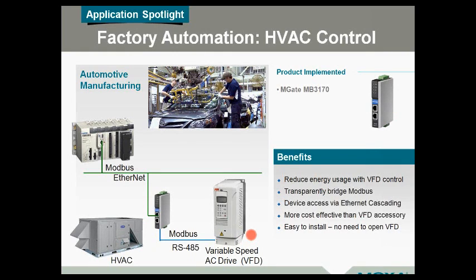A lot of these, almost all of these, have Modbus built in with a communications port that's used for initial setup. And all you need to do is be able to plug into that Modbus port on RS-485, come in through a gateway, and now you're available on Ethernet. And actually, I've done this myself.